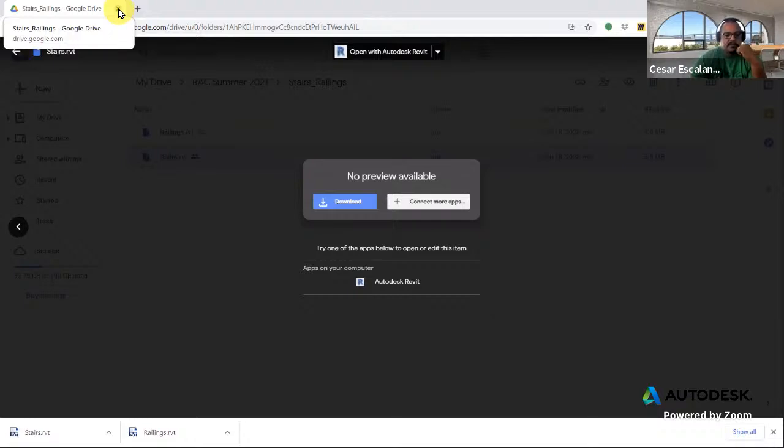In fact, I believe I helped a long, long time ago to create your typical interior partitions container file, which is a file that has, you know, 100 specific wall types. And what you do to use them is open the file, copy the types that you need, and then paste them into the project. So system families cannot be brought into the project as components, but they can be copy pasted.